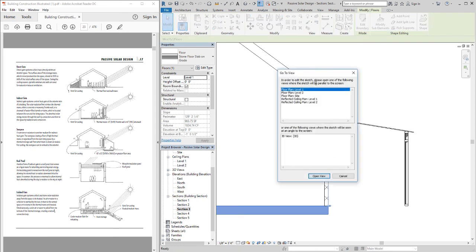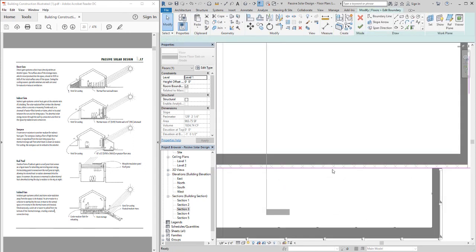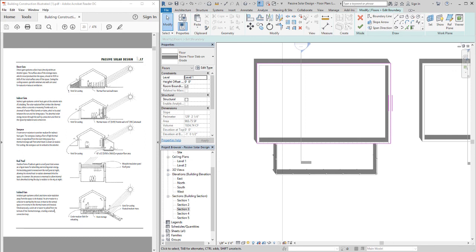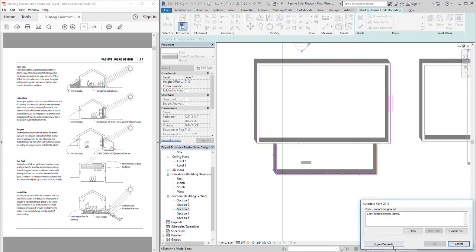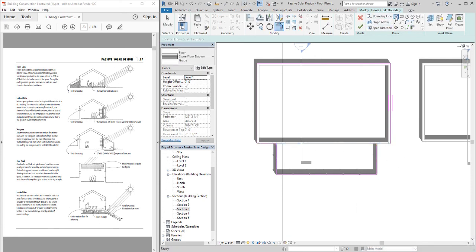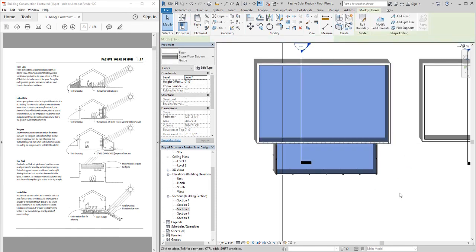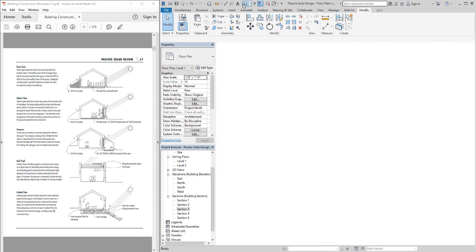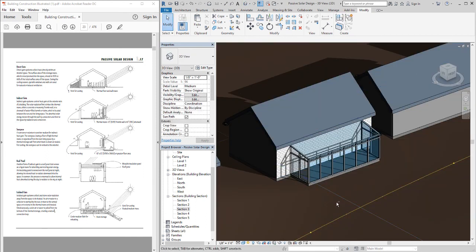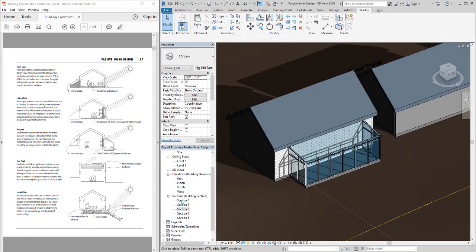So going into our third section view, I think I need to edit the boundary on this real quick to extend my floor underneath the sunroom. So let's do that. We'll pick walls, pick them up, and then use the corner tool on the end here and say unjoin, and then we're just going to have to snap nicely to our ends and check that off to have that extended. Let's go and take a look. There it is. Beauty, we have a floor underneath it.